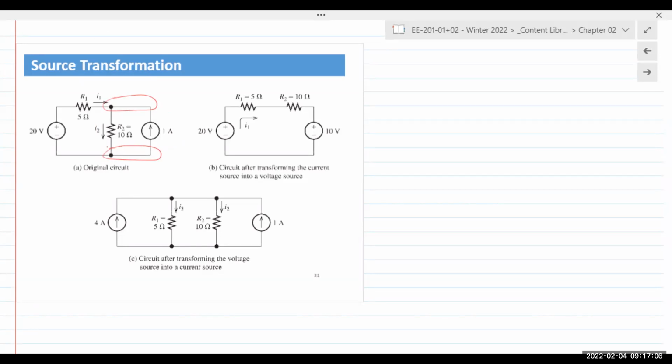At the same time, we can see that the voltage source and resistor R1 are connected at one single node on the top left. When you have a node which has 2 connections and not more than 2 connections, we can say those components are in series. And so it satisfies the criteria, and we can state that the voltage source of 20 volts is in series with R1.